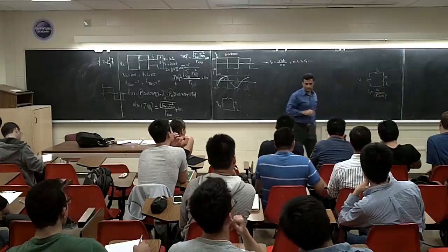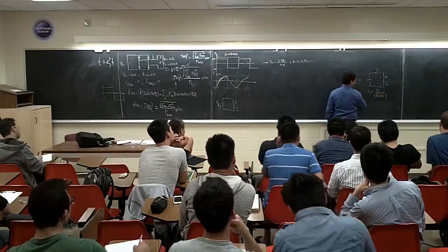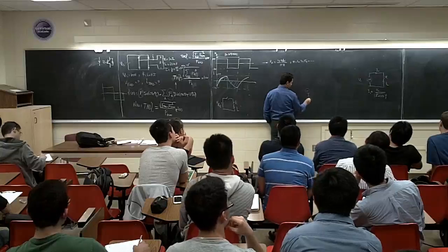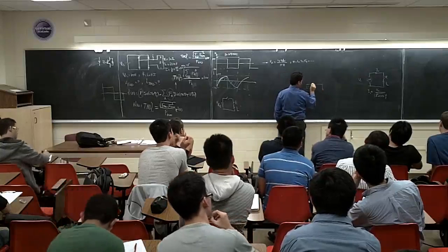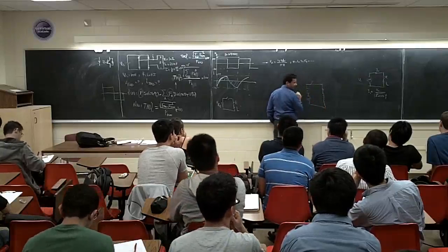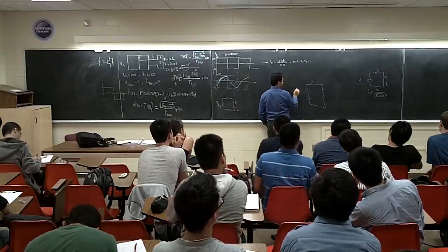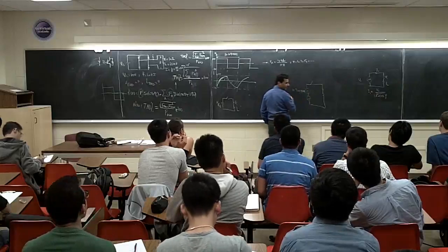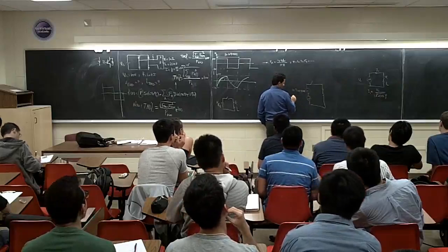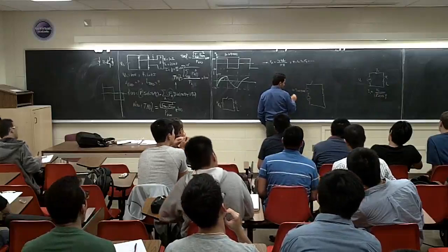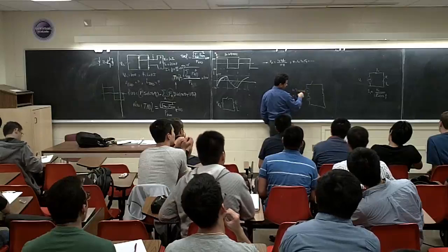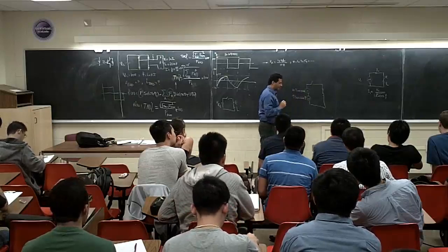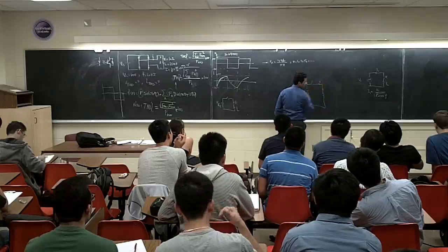But if I have a third harmonic, I'm not sure, have they ever tested this before in circuit theory? Usually this is what I like to give the student. I put two sources like this. If I was teaching circuit theory, I would give you a question like this. Okay, for example, this is 10 sine of 60 hertz, so it's going to be 377. And you have another source, for example 5 sine of 3 times this one, I don't know, 1000t. Do you know how to calculate this current?